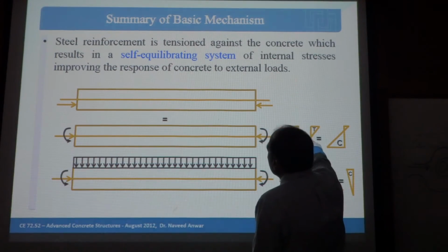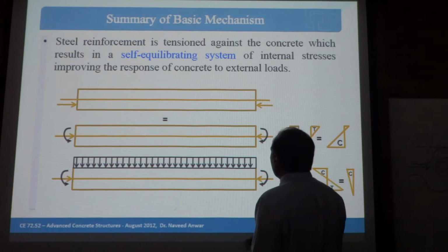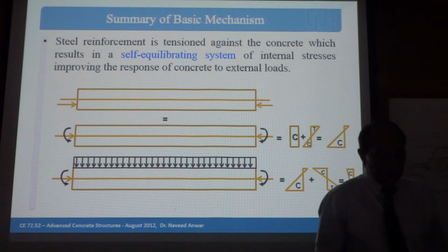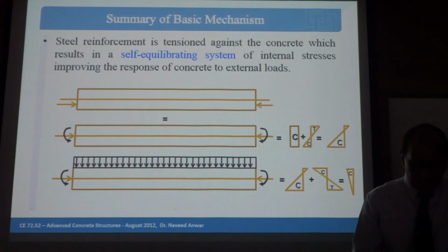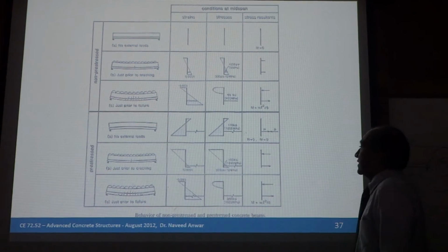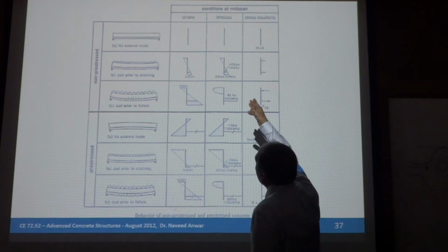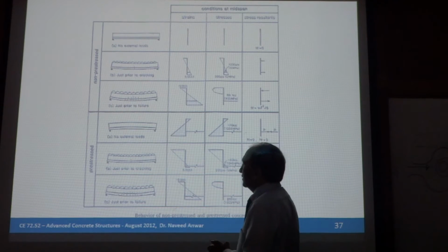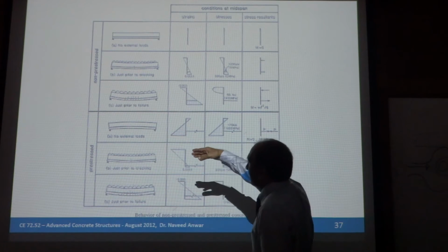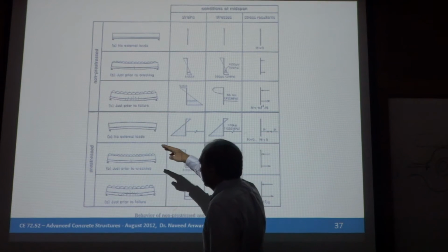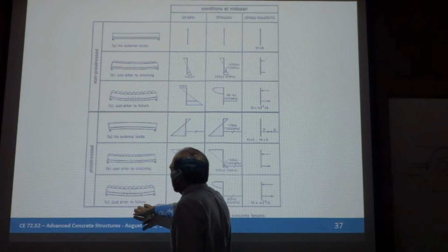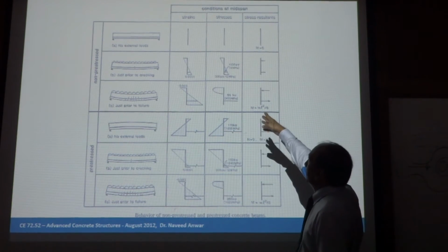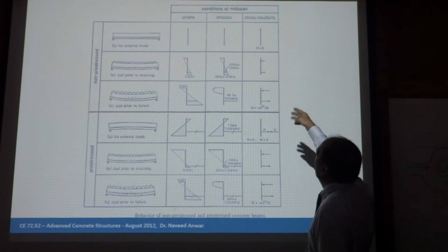So now this is the summary of whatever we have been talking about. We can convert that into equivalent moment and all of that stuff that I showed you. So ultimately, what do we have? We have plus minus. It is nothing but a plus minus game of the pre-stress behavior, and these diagrams tell you no pre-stressing, no external force, just prior to cracking, just prior to failure, different conditions of the stress diagram: strain, stress, and then stress resultant.